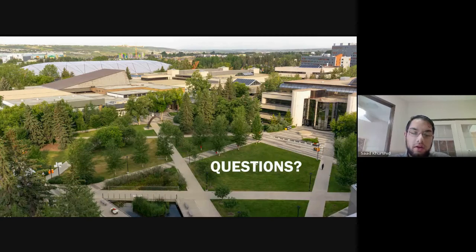Also with TransCAD, adding on to what Catalina and Zach were talking about, TransCAD assumes that pedestrians can only travel on the links you made. So TransCAD can't find the desire line for you. If there's an unauthorized path and you don't make a link for it, no pedestrians will take that path. Also, TransCAD can't identify jaywalking unless you make a link that allows people to jaywalk.